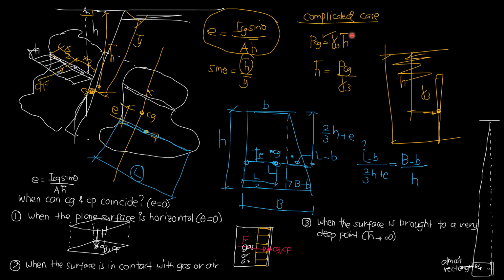To solve for bar h, if we encounter a complicated situation, bar h is not the distance from the centroid to the surface exposed to zero pressure, especially if there are layers of fluid. The idea there is we convert all those liquids into a single liquid.